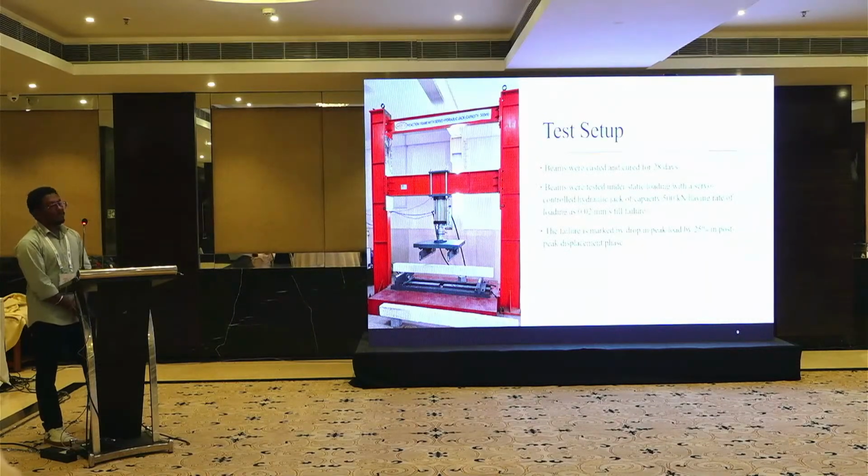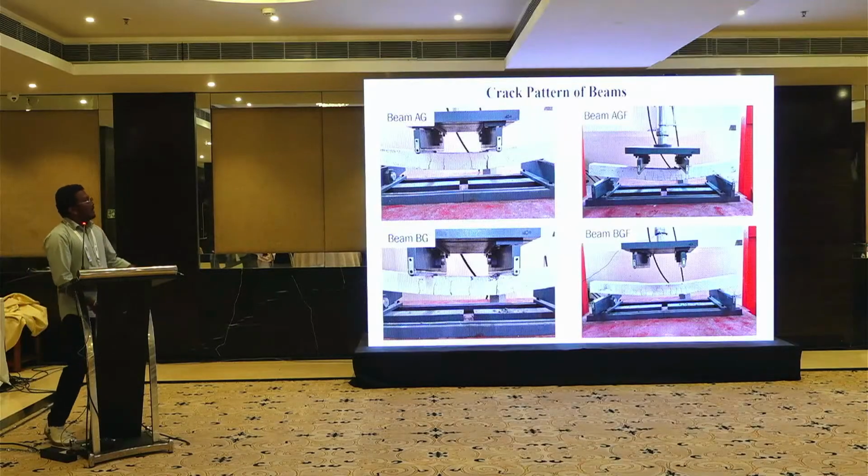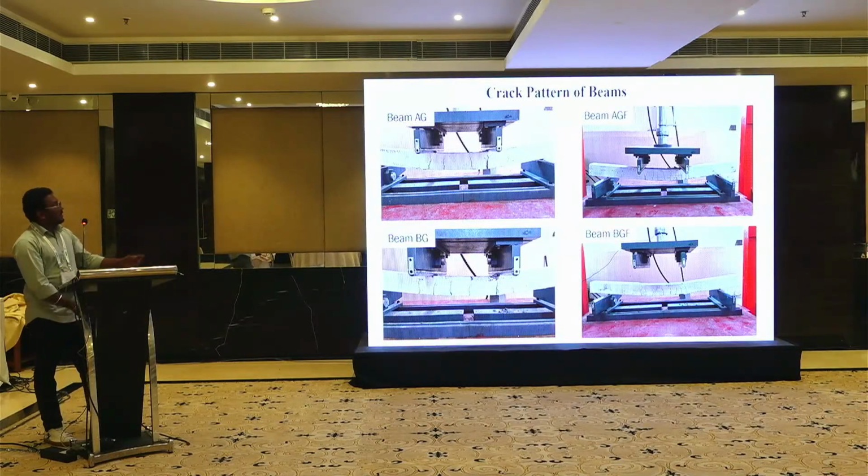And test beams were cast and cured for 28 days, and beams were tested under a servo-controlled hydraulic jack of 50 kilonewton capacity at a rate of loading of 0.02 mm per second until failure, and at 25% in the post-peak displacement phase we marked the failure. And these are the crack patterns observed in the beams.